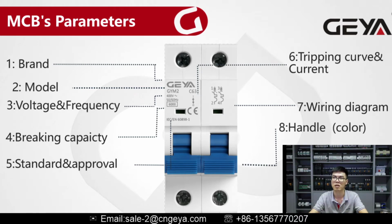And number 6, you can find the tripping code and current. There is a number and a letter, C63. This letter C represents this MCB is a C curve, and this number 63 represents its rated current is 63 amperes.